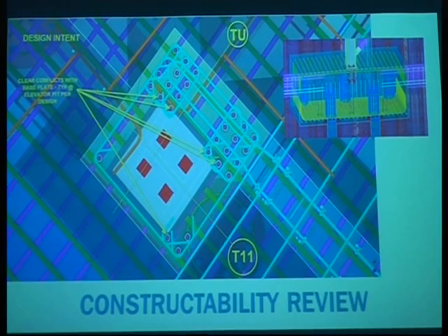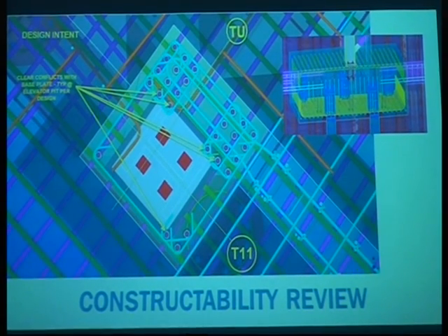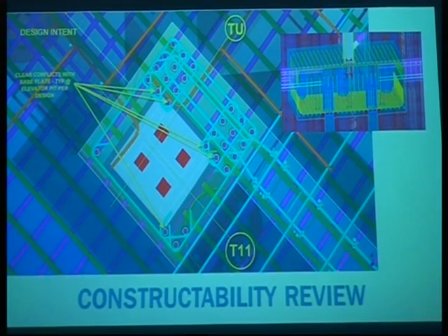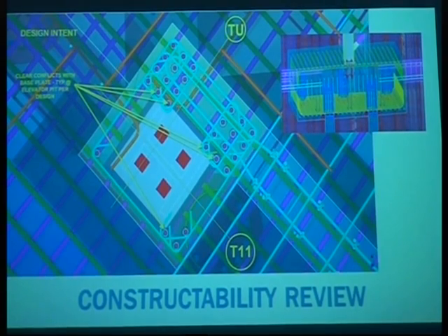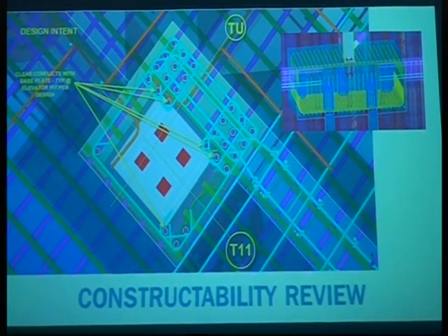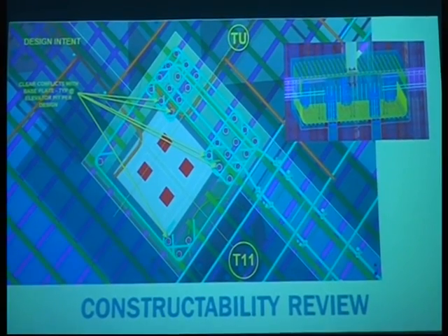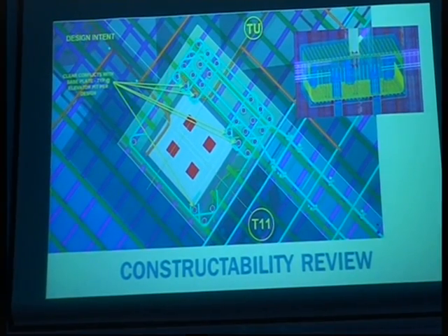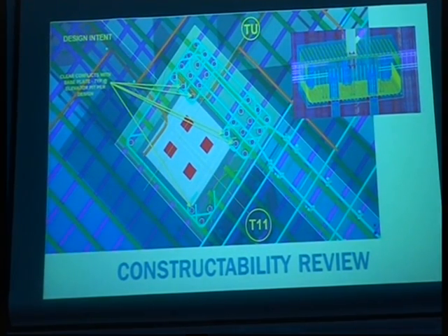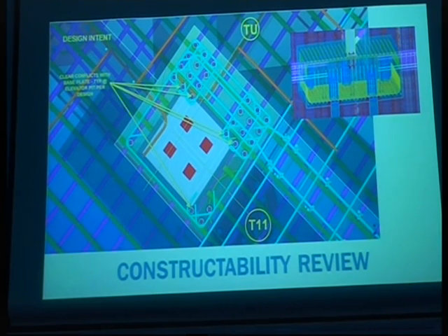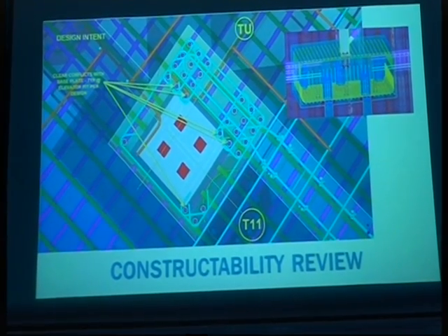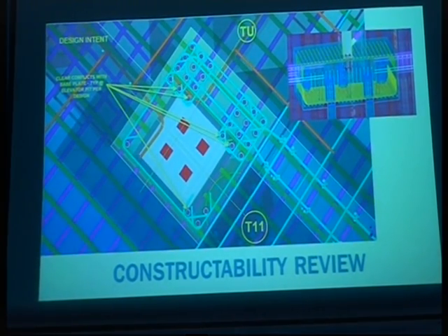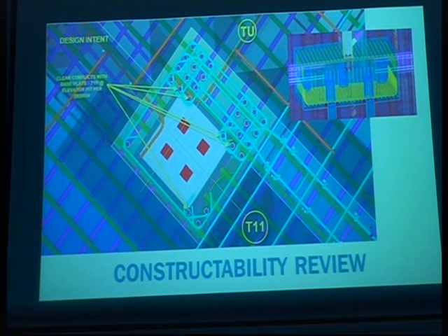Like I said, we model up to a quarter of an inch in diameter. A quarter of an inch in diameter, that's probably like, let's say, a half centimeter. And so we even model our rebar, footings, beams, you name it, to move them in places where the structural integrity is still achieved. And so when you think about BIM, think of the right level of detail. So those are the key elements: how much do I model, and what level of detail do I go into?